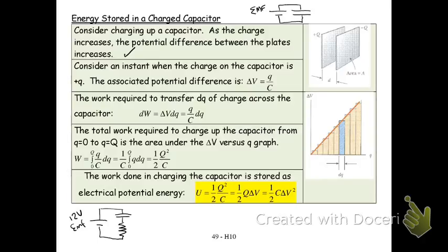So I would see, if I got a voltmeter, my voltage across the capacitor, the potential difference, increase in time because the charge takes time to get onto the capacitor. So if I plot my potential difference across the capacitor versus the charge on the capacitor, this is what I'd see. Now, if you think about it like this, well, why isn't it 12 volts immediately? Because you can never make that circuit. You're always going to make this with a little bit of resistance.